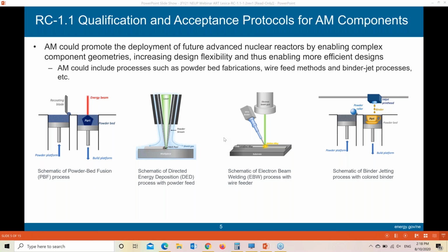So in order for us to focus this work, we want to concentrate on 316H grade, and even though 316H can be used for high temperature, we want to fix that at 650C and a moderate design lifetime of 100,000 hours, so that researchers have a target to demonstrate the developed methodologies against these conditions of temperature and lifetime, because as far as the raw metal behavior is concerned, we know quite a lot about 316H.